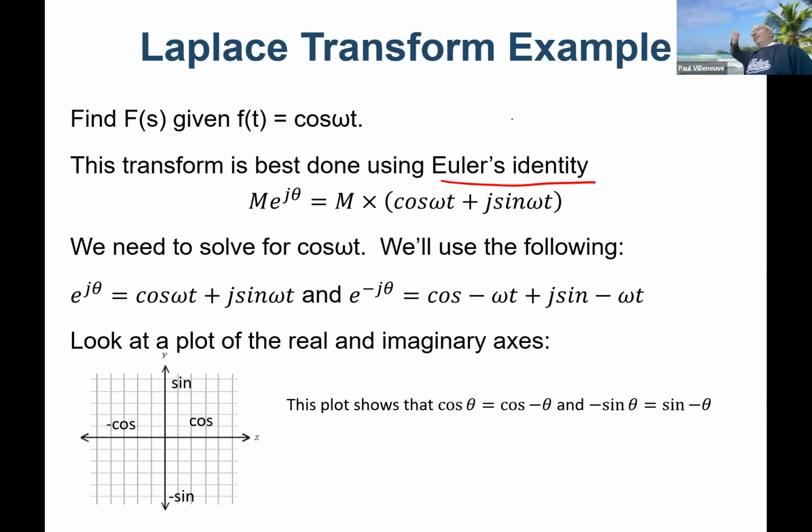So you've all done Euler's identity time and time again. If I have a voltage source of 120 volts at an angle of 45, right? That's AC circuit analysis. You remember doing that? That's not really 120 at an angle of 45. If you wanted to write this mathematically correct, it's 120 e to the j 45.